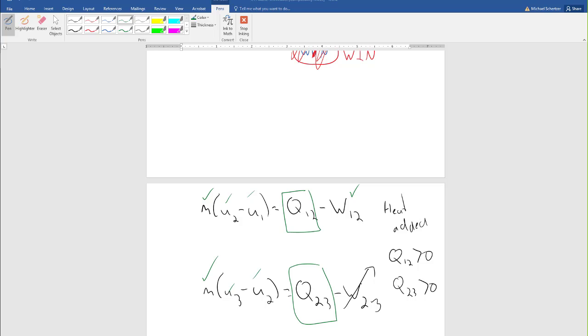And then other than that, basically everything is building to what we've done here. So do you know how to find work? It's the integral of PdV. Do you know how to fix states for steam like we did today? Or next class, we'll do an example with ideal gases. It doesn't sound like much when I say it in 2 sentences, but it's enough. Yeah, it's a lot.